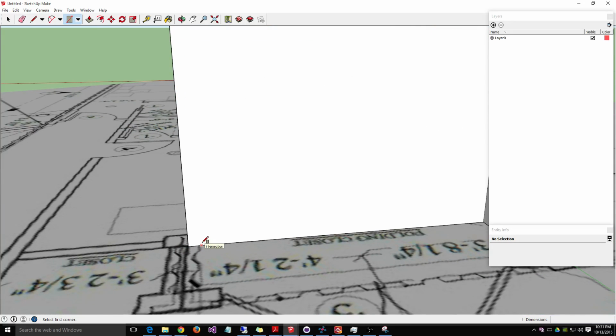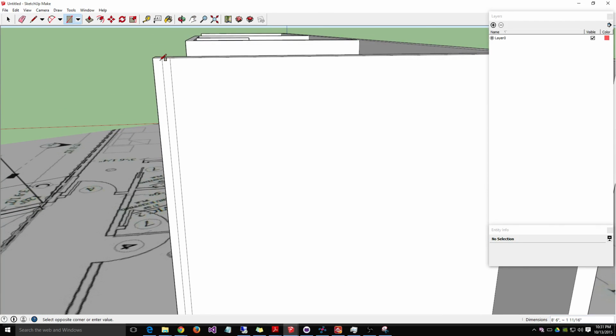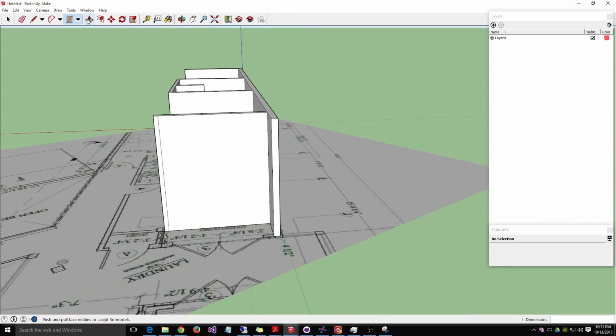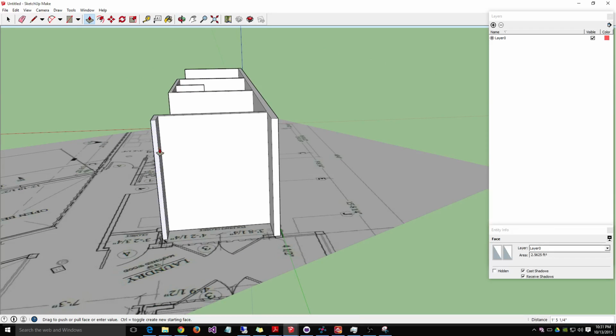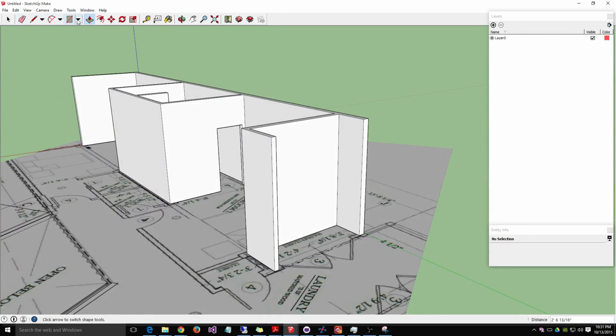I'm still not there, so the things that I'm doing are still okay. So far. But I'm going to get very close to not being manifold. And if it's not manifold, and you want to 3D print it, the 3D printer wouldn't know what to do. As a matter of fact, the STL file would be invalid.